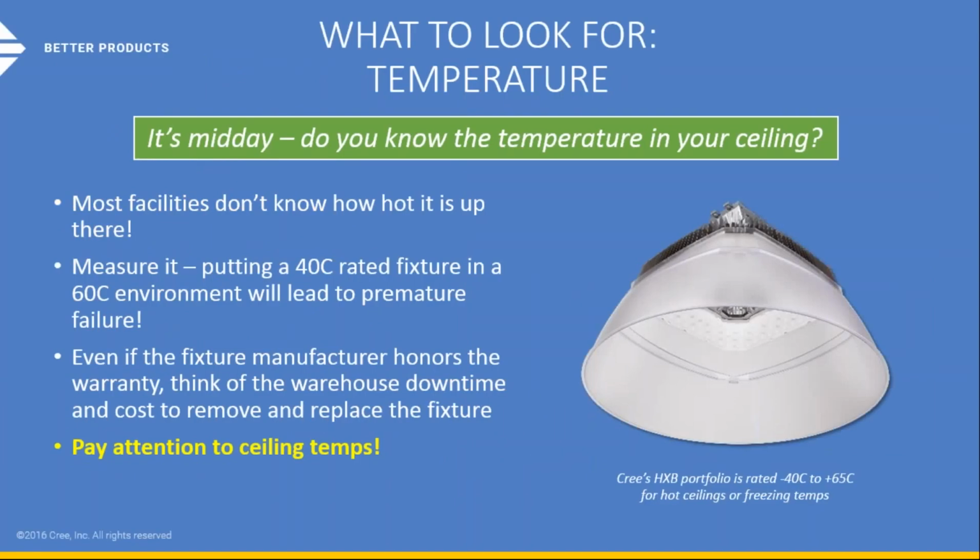So temperature. These are things that have to be put into consideration, like I mentioned earlier. So really the question is, do you know the temperature in your ceiling? I trust that some of you actually do know the temperature in your ceiling. If you're in a facility that's doing any kind of metalworks, you probably know that you're in the 60 degrees Celsius range, and the products that you're going to put up in those ceilings are going to have to endure that kind of temperature and continue to operate.